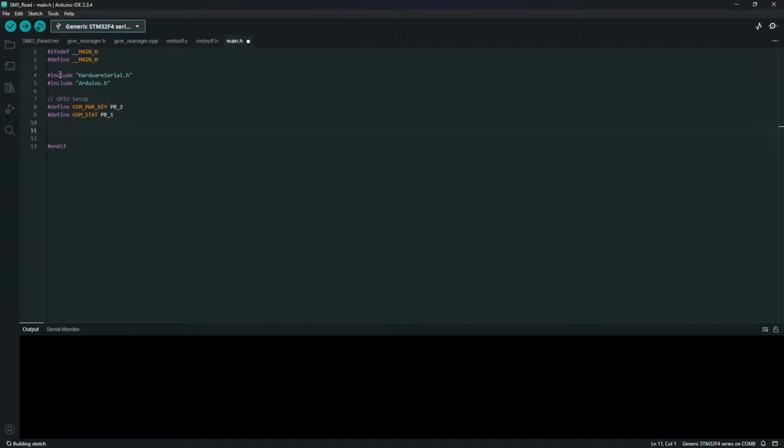On top of that, we want a UART connection as well. With our UART, the serial monitor will automatically be on the USB serial, and then we want an additional serial connection that we're going to be using to communicate with our GSM modem, and we're going to call that GSM serial, and in my case that will be assigned to serial 1.